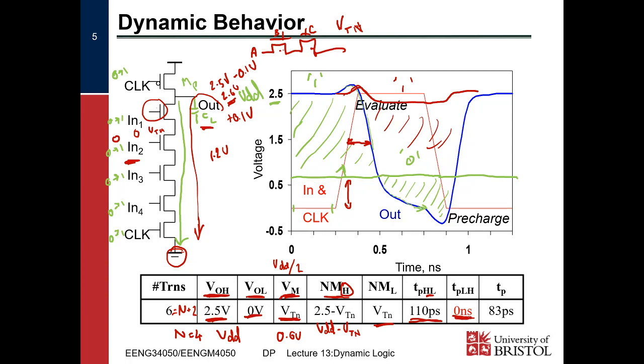This is great because it means that we don't have to worry about charging our signal up, about the sizing of the PMOS transistors to make sure that we get a balanced propagation delay, because our low to high is 0 all the time. So we only have to worry about the delay on our NMOS pull-down network, right? We don't have to worry about electron-hole mobility differences.